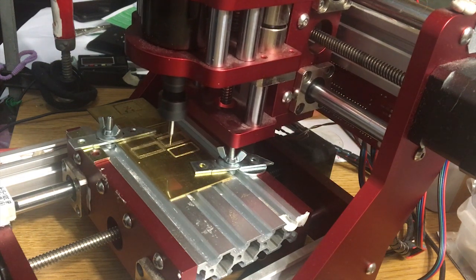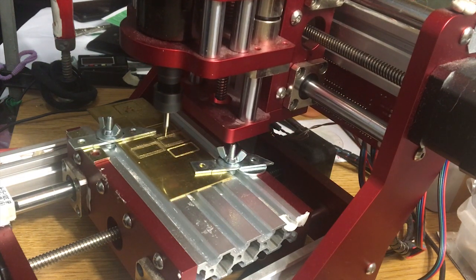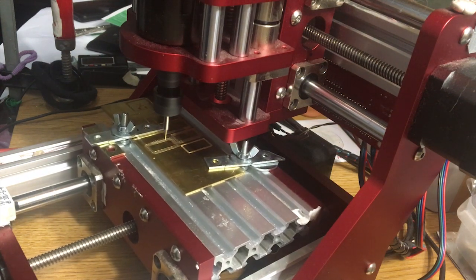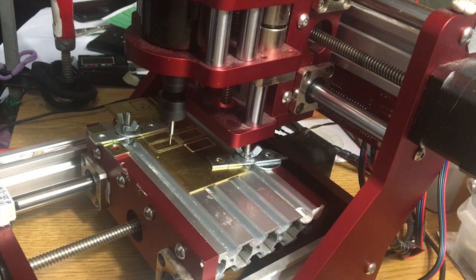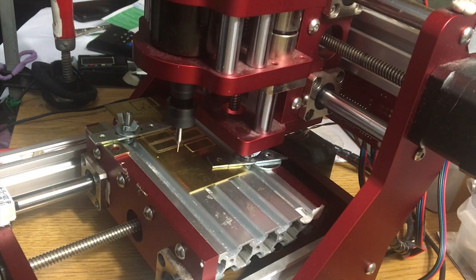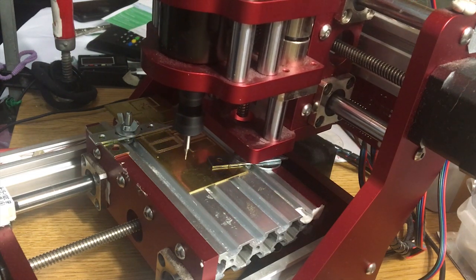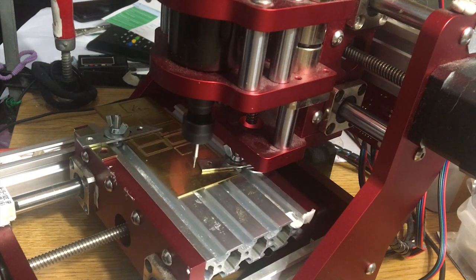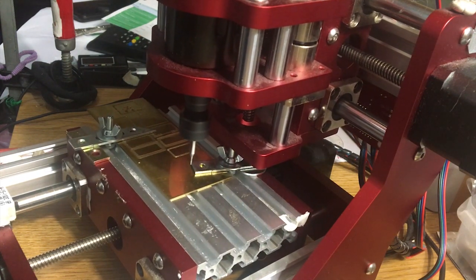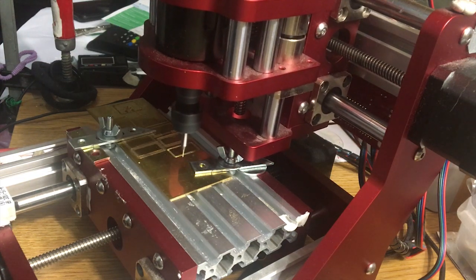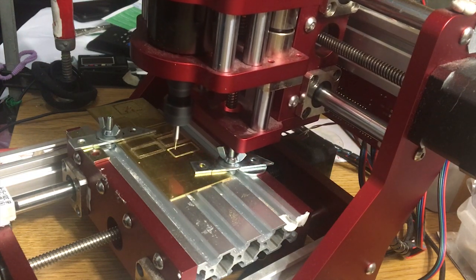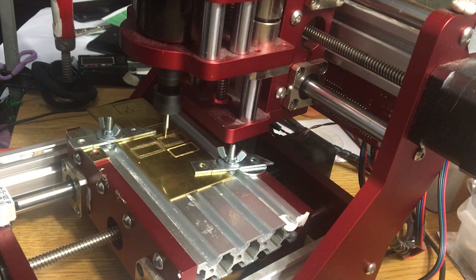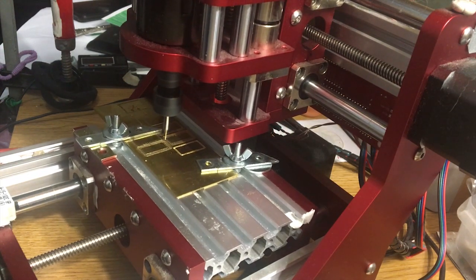The CNC runs as many times as is necessary to write the value of the design. In this case, I use 0.01 millimeters for every cycle to prevent breaking the bit, because we work in brass metal.